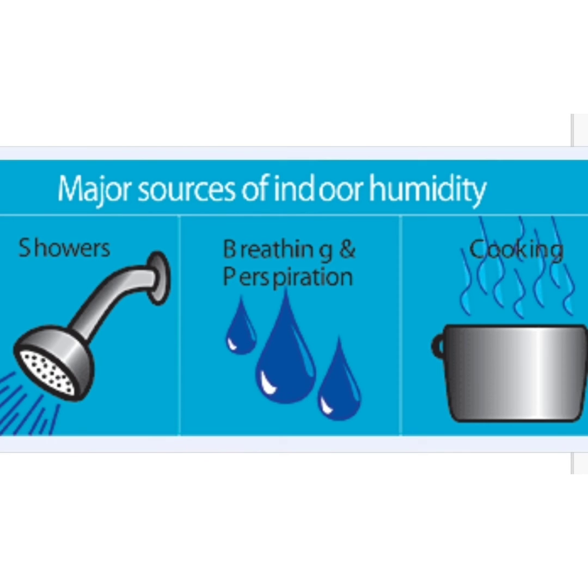But this video did start off acknowledging that humans add to the moisture in the home. And that's true. But think about when we need a humidifier the most. It's in the middle of the night when we're asleep. How much moisture are we really adding to the building? We're only breathing. We're not cooking or showering during that time. So good discretion needs to be used whether we really factor in that humidification that humans add back to the building or not.